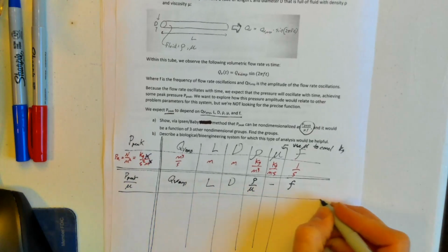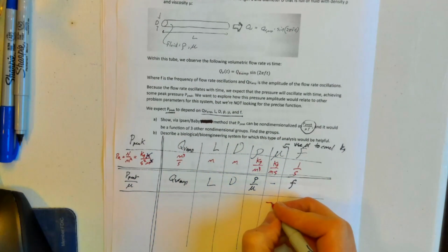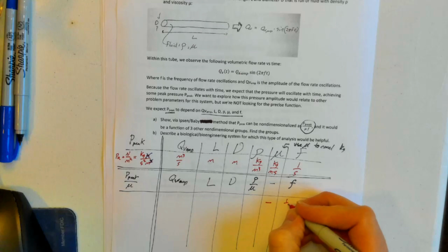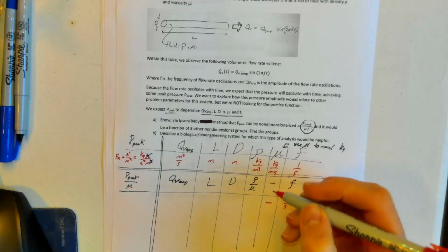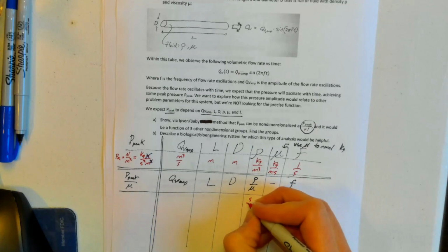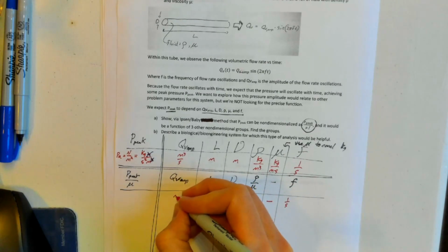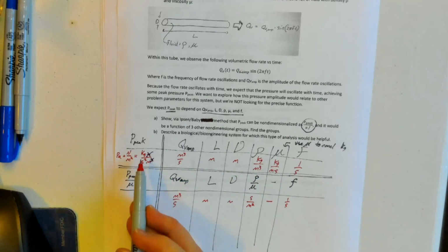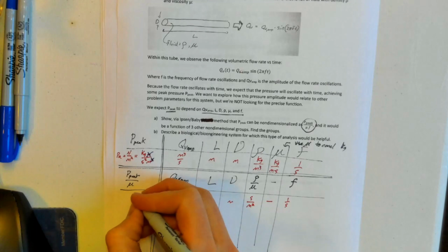So now let's write down what all the units are of our new things. We've gotten rid of viscosity. Frequency is still 1/seconds. Kilograms per meter cubed divided by kilograms per second ends up having seconds per meter squared as its units. This group has seconds per meter squared. We still have meters cubed per second, and then kilograms per second squared divided by kilograms per meter second. We end up with units of 1/seconds right here.